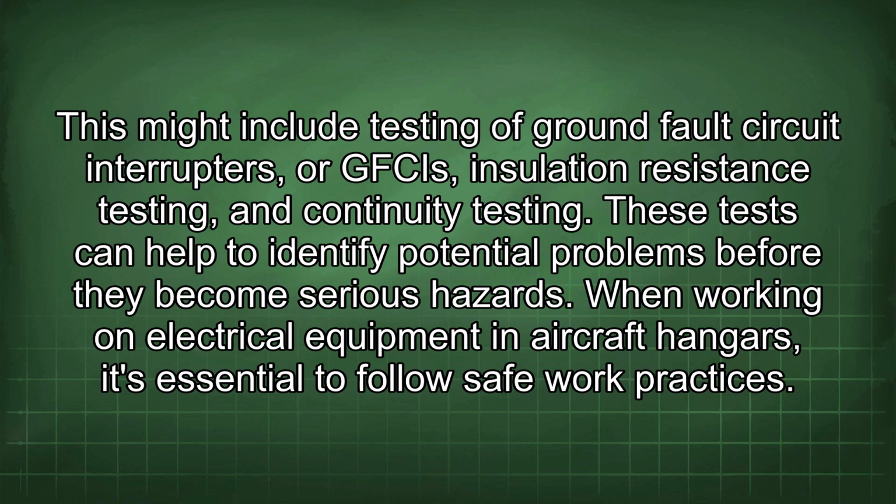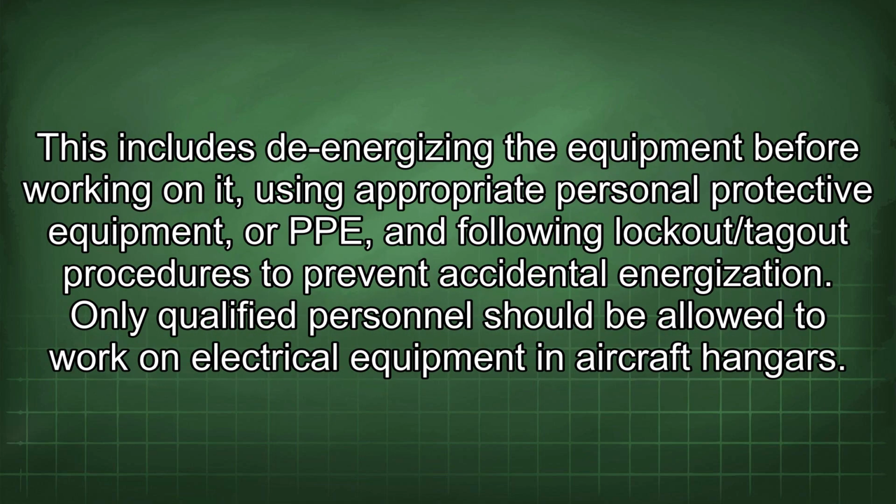When working on electrical equipment in aircraft hangars, it's essential to follow safe work practices. This includes de-energizing the equipment before working on it, using appropriate personal protective equipment, or PPE, and following lockout/tagout procedures to prevent accidental energization.